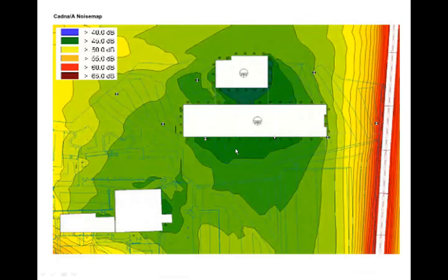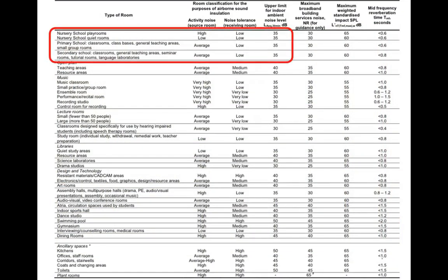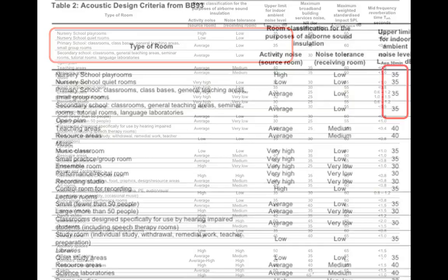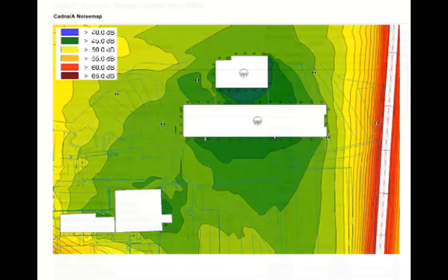this region on site, which is experiencing about 45 decibels, is unlikely to meet the acoustic criteria if we open the windows for natural ventilation. Okay? So that's really critical. Very early on in this project, the acoustics of the site are starting to define the principles of ventilation, the principles of the facade, and even the principles of the structure of the building. Okay, so there's just highlighting our 45 dB.